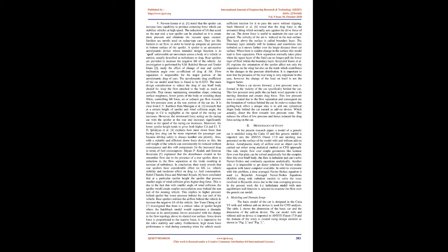Flow separation is responsible for the major portion of the aerodynamic drag of cars. The aerodynamic drag coefficient of the car model used here is found to be 0.3233. The main design consideration to reduce the drag of any bluff body should be to keep the flow attached to the body as much as possible. That means maintaining a streamlined shape, reducing surface roughness, having fewer joints on the body or avoiding sharp fillets, controlling lift force, and directing air or exhaust gas flow towards the low pressure zone at the rear portion of the car, etc.